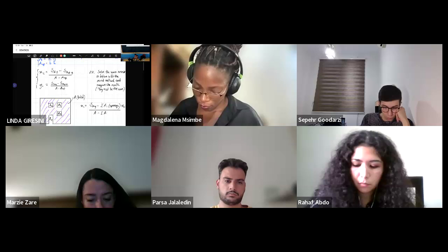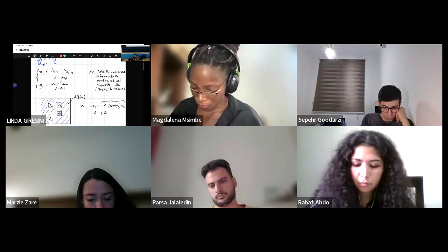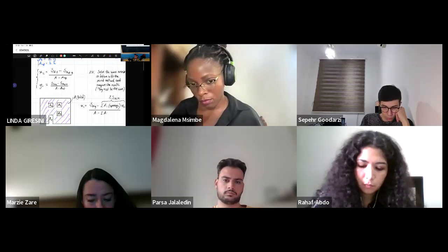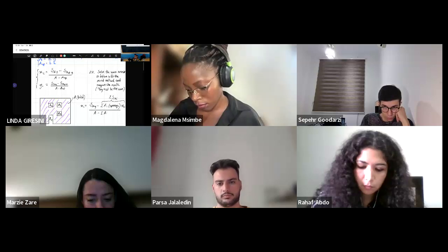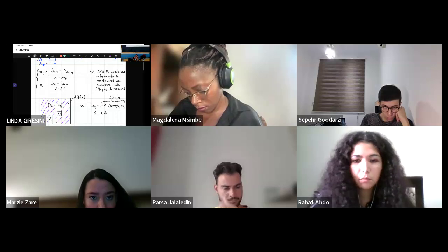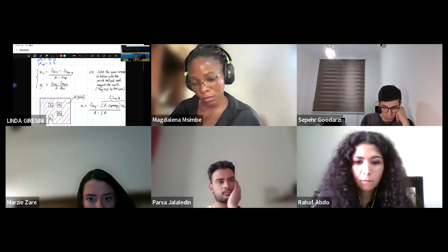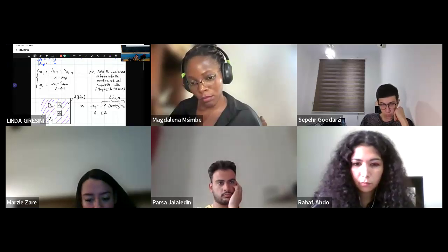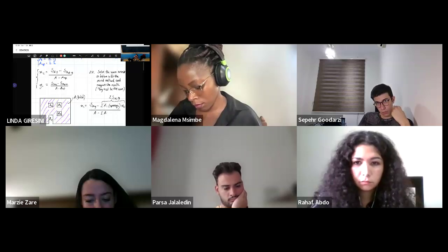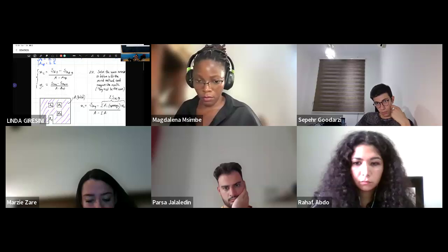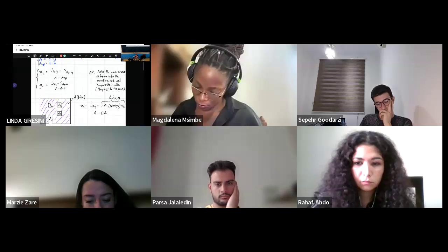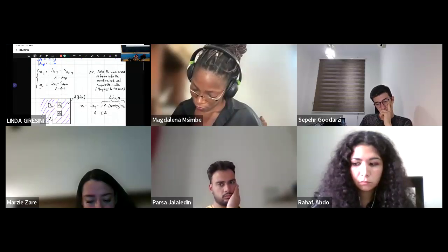So this is the sum of the static moments of the openings with respect to Y. It doesn't matter to me whether you write S_X or S_Y every time. The important thing is that you refer to the correct axis. If you are doing the calculation with respect to the Y axis, you will use X. If you are doing the calculation with respect to the X axis, you will use Y. Always the distance.